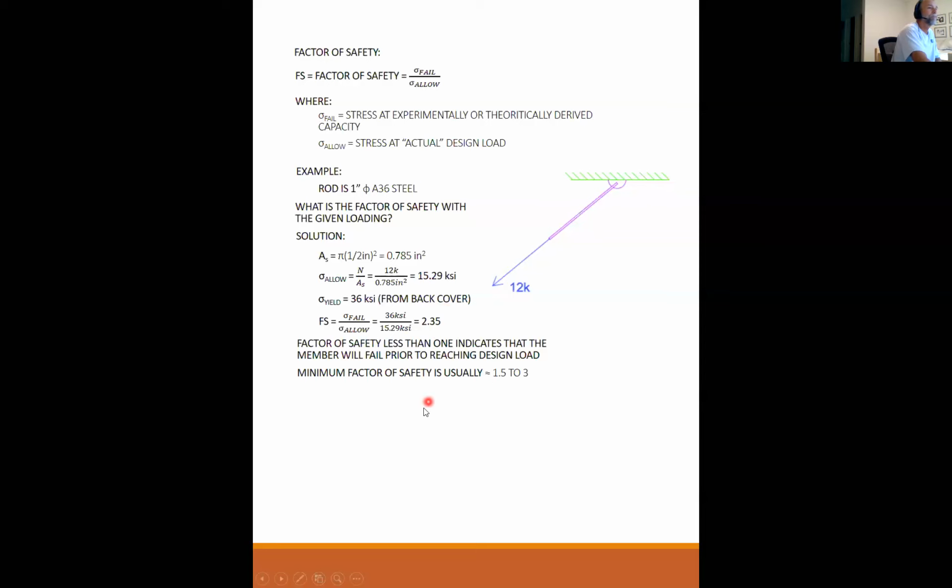We still do some materials this way, but most materials now are based on capacity-based design. And what is the difference? Capacity-based or strength-based or LRFD-based, you'll hear these terms, design looks at a reduced ultimate capacity compared to a factored load effect.